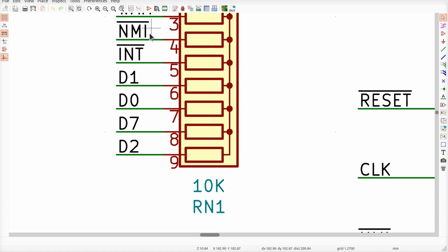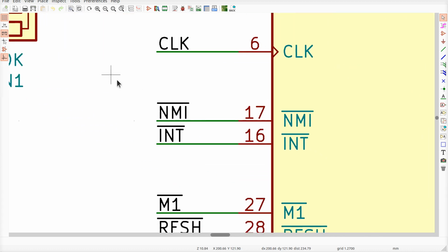If you were to use such a signal, where you find it used is things like if your power supply is shut off and you know that the hold-up capacitors, the big filter capacitors, will discharge in 400 milliseconds or something like that, you might assert the non-maskable interrupt, which the Z80 then would recognize as the power's about to shut off.